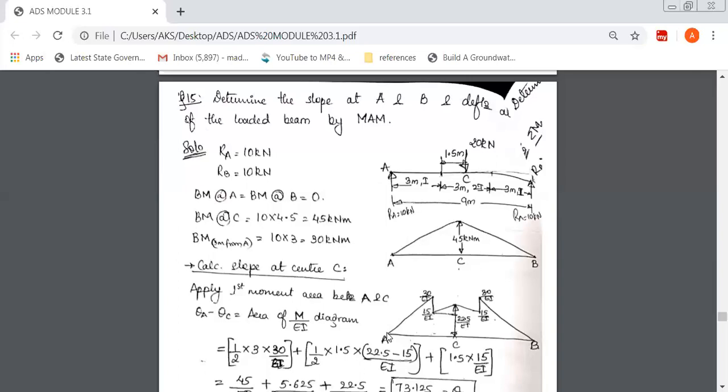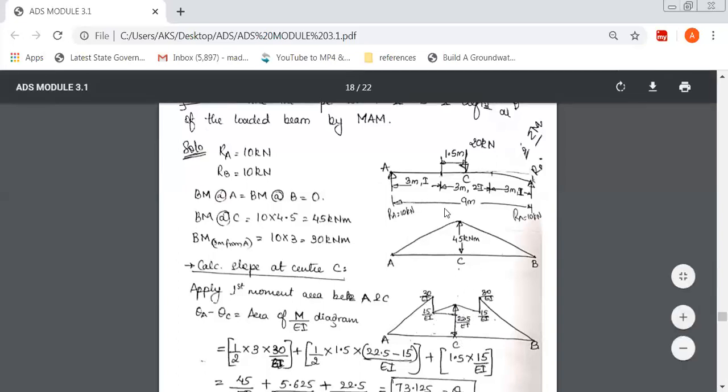What you'll do is, first mark the points here. All these points should be relative to the magnitude. There should be some difference. You see here, 30 should be maximum. Then 15 should be lesser than that. And 22.5 should obviously be an intermediate value, slightly in between. So after this, just mark all these points. And similarly, this would be just the replica, because it is exactly at the center, a symmetrical load. So when you flip it over, it should be the same. So obviously at the next third meter it is 15 over EI, 30 over EI. This is just the same.